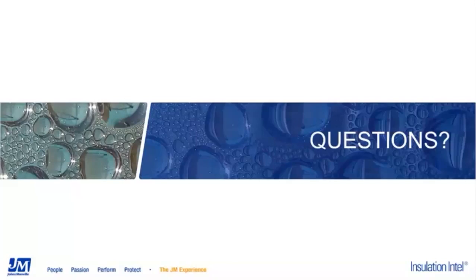All right, that's all nice and easy to say, and yet we sometimes have the necessity to have penetrations. Maybe you have a vertical run of pipe that has to be supported internally. There are certainly valves in the system, and every valve is going to have a valve stem of some sort that most likely penetrates the insulation and vapor retarder system.